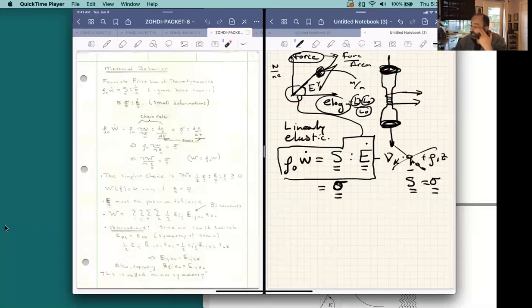They're immaterial; second Piola-Kirchhoff stress or Cauchy stress, they're one and the same at the smallest scales. And the Green-Lagrange strain, recall, is equal to 1/2 (F transpose F minus 1). In the limit, that becomes the small strain tensor when the deformations are small. So in fact, this becomes sigma times epsilon dot.